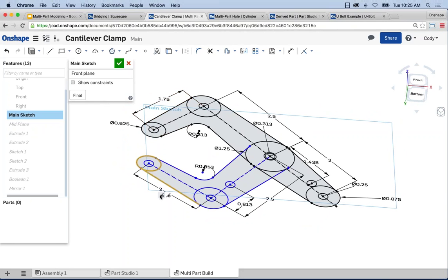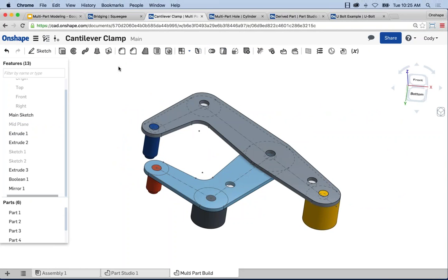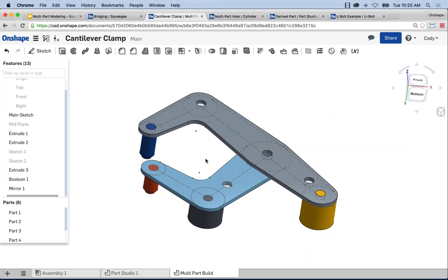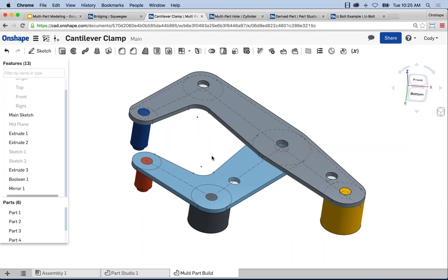There's really not a limit to this. You could have hundreds of parts referencing a single Part Studio. And that means that when I make a change, so I just changed 2 dimensions, everything automatically updates. So you'll notice the pin locations, I didn't have to shift them around because the references they were attached to moved, they moved as well. Okay. So again, that's probably one of the biggest benefits to building this way, it's very easy to change. If you need to make an iteration to it, you can change 1 or 2 dimensions and many different parts will change with it.